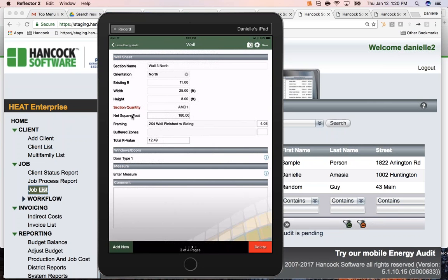Art, what is that square footage here doing? It's part of the load calculation. It's the same in all of the heat transfer surfaces, whether floor, attic, or walls. It contributes to determining the size of the load. The higher the net square footage, which is simply subtracting the windows out that you put in, gives you the load coming through that wall, along with the degree days and the basic building science algorithm.